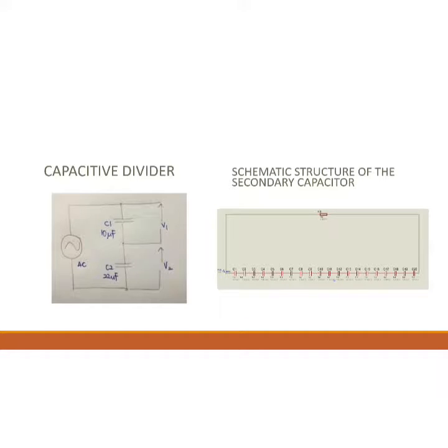And next, the question is: by realizing your knowledge of Electric Circuit 1 and 2 during the first year of study, draw a proper diagram to show the capacitive divider for the measurement, by considering a high voltage level to a lower voltage level. Okay, for the capacitive divider, the circuit consists of two capacitors. Based on the theories, the higher the capacitance value, the lower the voltage value.